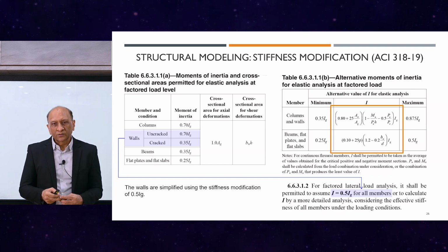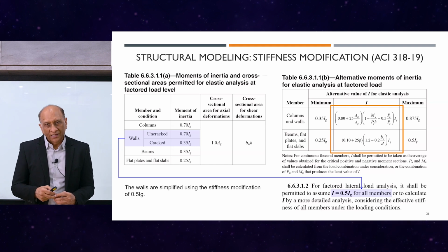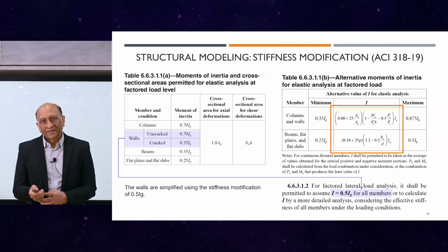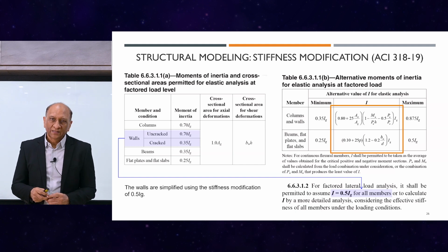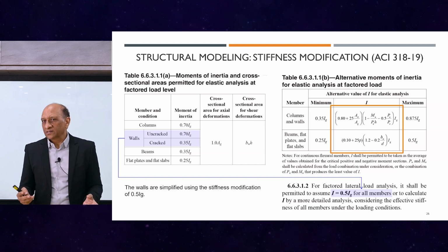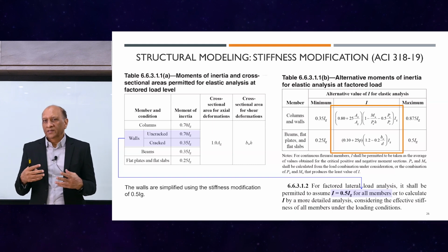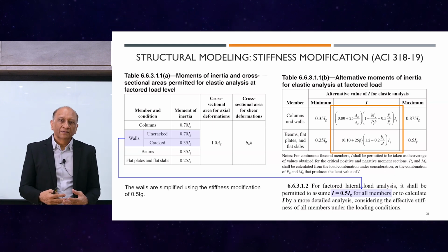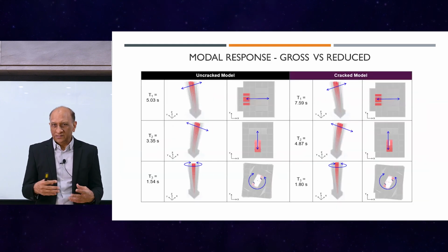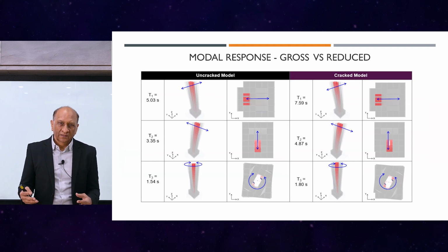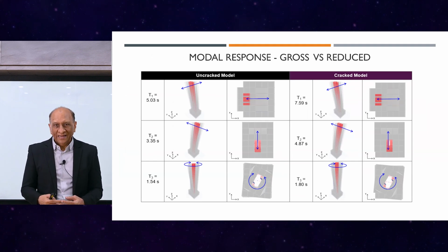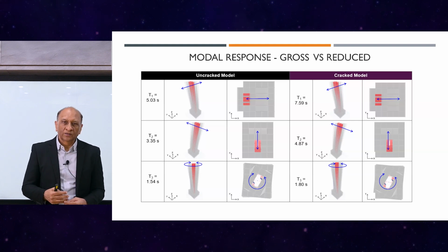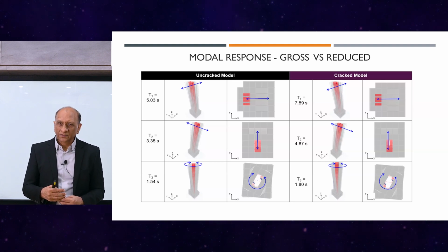Then we can now see the change in the base shear, and you can see here that there's a reduction of about 18% in both directions due to using the cracked section. So this is quite significant: the estimated base shear due to earthquake, of the same response spectrum and same structure, is now calculated to be 18% less than the one with the gross section.